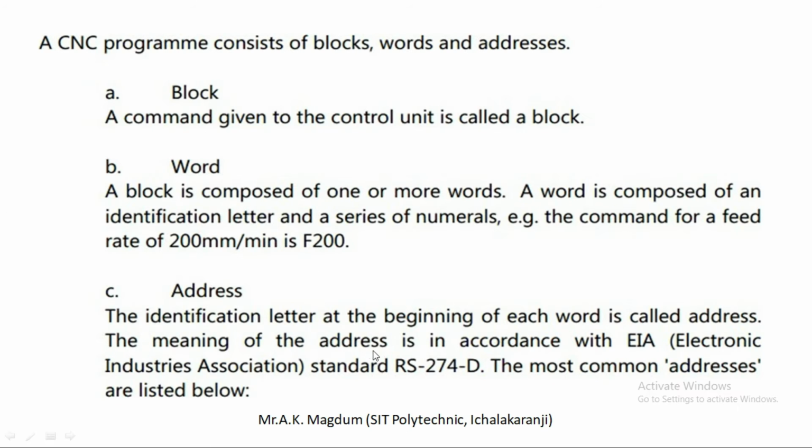Here, the meaning of addresses is in accordance with the EIA, Electronic Industries Association, standard RS-274D. The most common addresses are listed below. Here, there are so many addresses which are required for the preparation of different programs. But the best example, as all of you observe in this slide, is F200. F is the address word, and it is clearly indicating that F means feed. So that is a simple way.